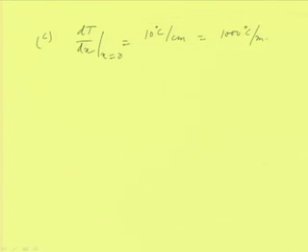And the third part of this problem is that we have to find out, it is being given that dT by dx at x equal to 0 is given as 10 degree centigrade per centimeter. So, this is equal to say 1000 degree centigrade per meter. This is very important, we have to be very careful about the unit. So, dT by dx equal to 1000 degree centigrade per meter,